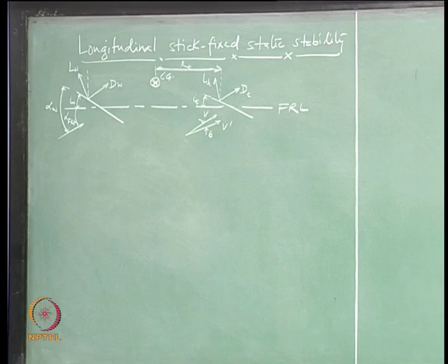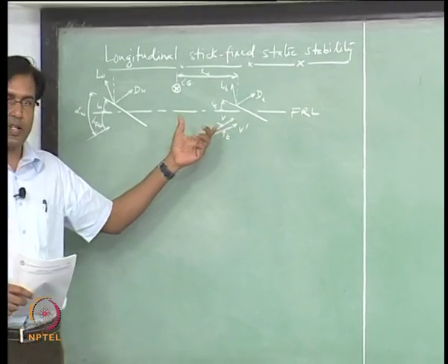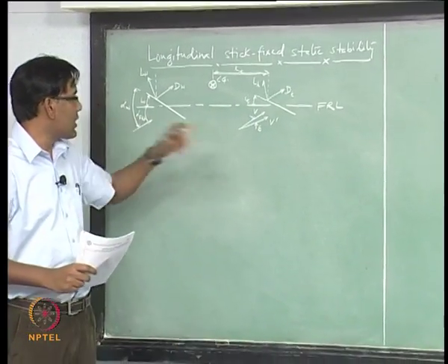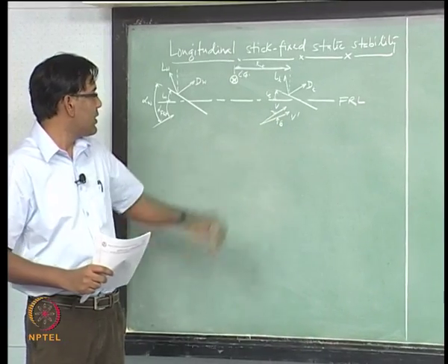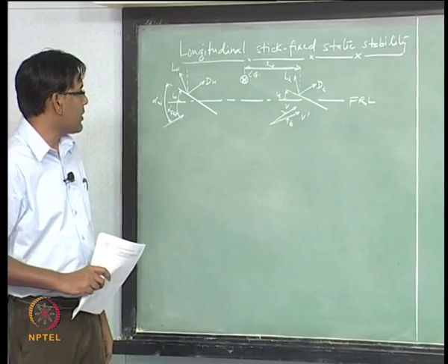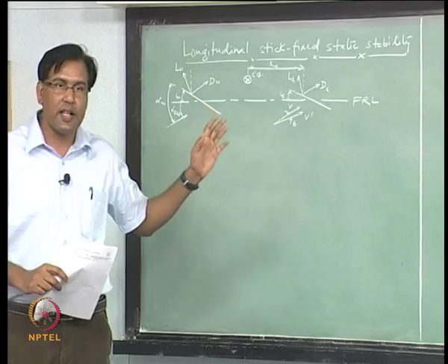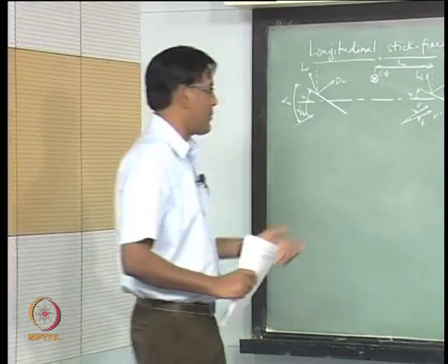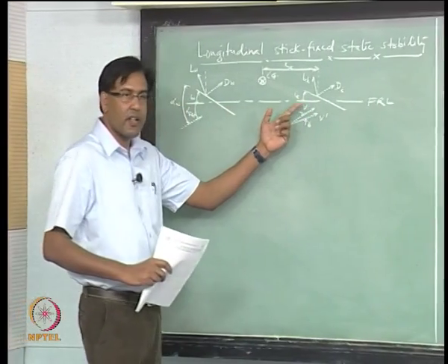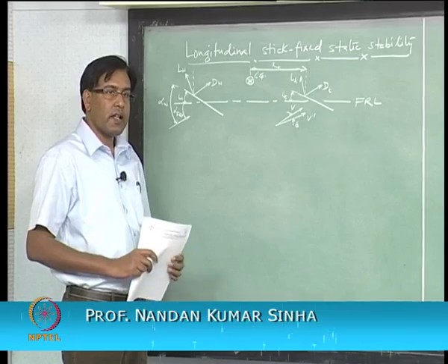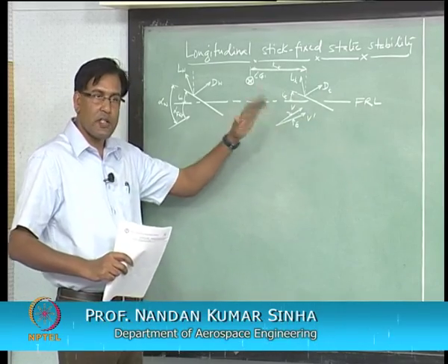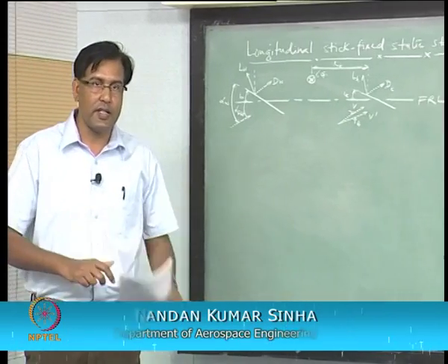and after making some assumptions based on some distances which were small, and that this tail is lying in the wake of the wing, right. So, there is a downwards angle, or I would rather say the tail is lying behind the wing, okay, and because of that there is a change in this velocity vector, right, not only in the magnitude, but also the angle changed, right.